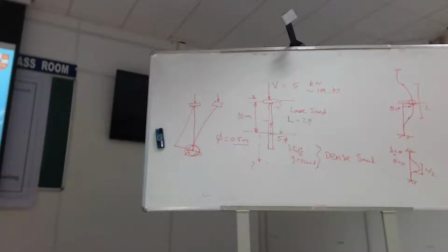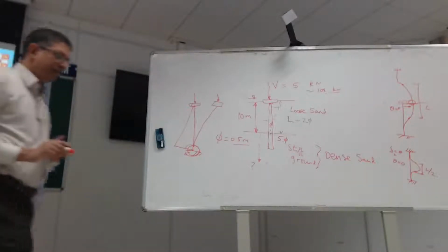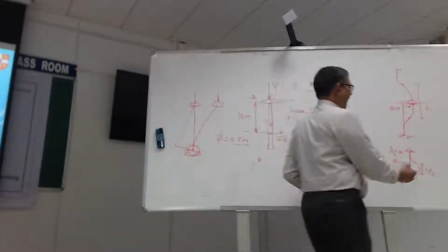If you move the pile into the liquefied soil, the initial thinking people had was, it's liquefied. What can it do? It's like liquid. Liquid does not offer any resistance, not much anyhow. It turns out that if you take liquefied soil and shear it, it will go hard on you. There's a good reason why it is, but you need to know basics of critical state soil mechanics.